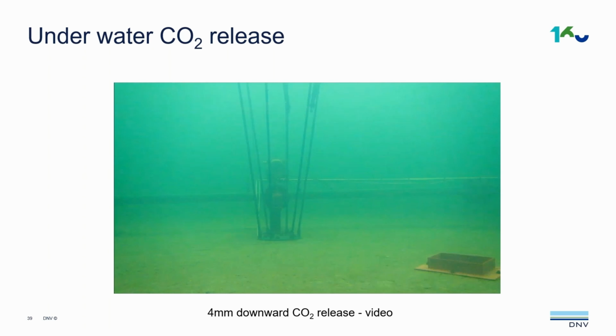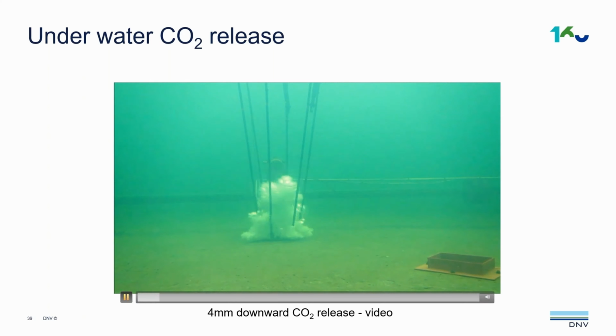This is another experiment, this time recorded underwater. In this scenario, the release direction is downwards for a 4 millimeter hole. Because the release is downwards, it impinges on the floor, which will result in a wider plume. The upward release has more of an arrow shape and is narrower.